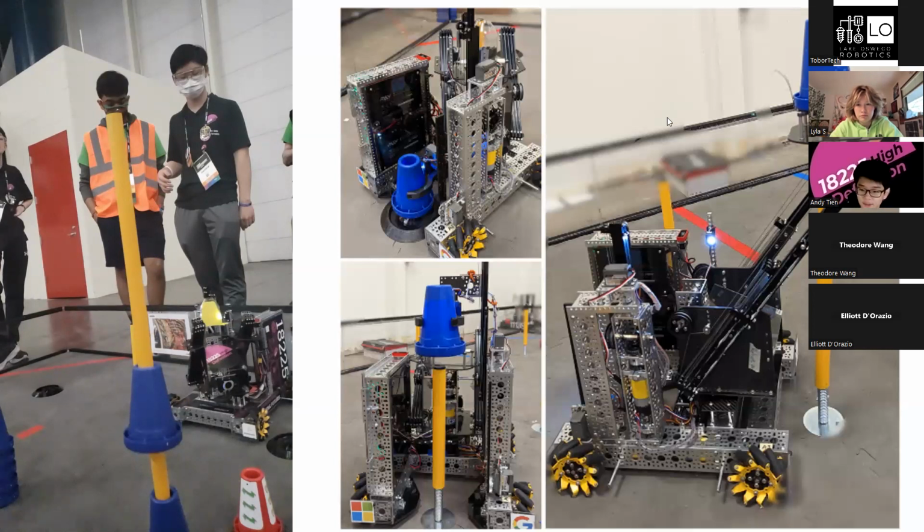The second one is the extension may be knocked out of place when attempting to deliver. Once again, that is resolved simply by the season criteria. The next point that is brought up is transfer being a point of failure. Transfer was certainly a point of failure for this robot. The main thing was that the cone could have a little wiggle room, depending on how high we grasped it. How we adapted to that is, if you look on the rightmost picture, you can see there's actually a color sensor mounted on the delivery.